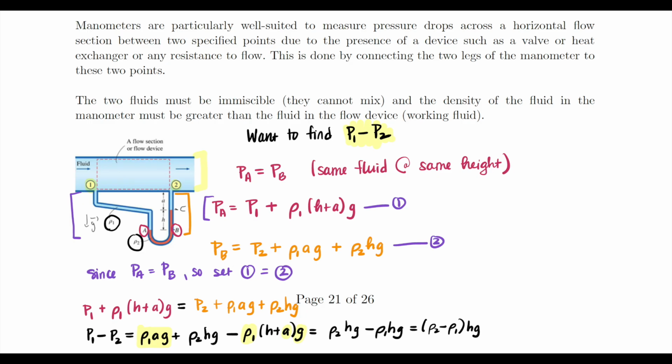And before we do that, I just want to put a quick pause on this. When we did this layered fluid system, you'll notice that we ended up with our reference pressure at the very top plus rho GH of each of the individual layers summed together, right? Which kind of makes sense because we're adding up the weight of the individual layers over top of us. Okay, so we're going to do the exact same thing here, except now we just have 2 layers, right?